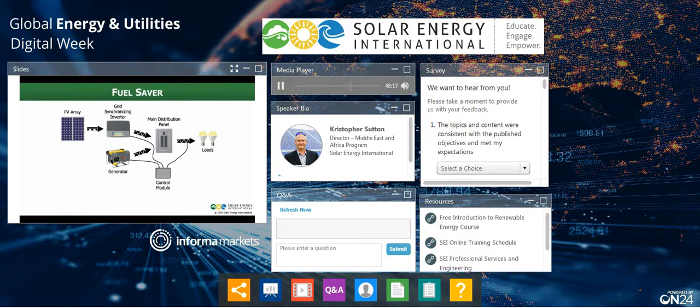There are multiple inverter and generator combination products out there, and multiple companies doing this. Usually this is on the 500 kilowatt to multiple-megawatt size of systems. Usually we see these in remote towns and villages that have their own diesel gensets. We see them at mining operations or sometimes remote industrial operations where they're running off of generators only.